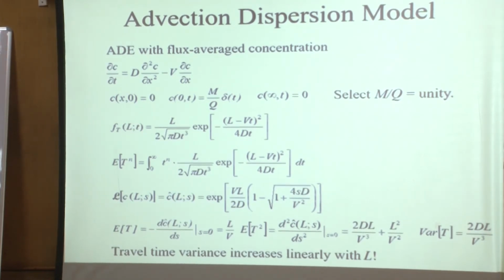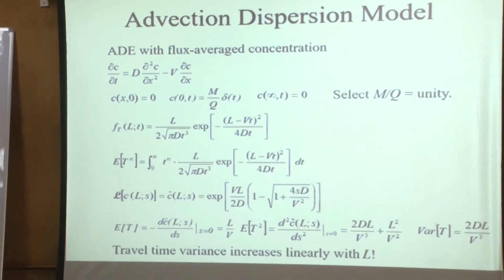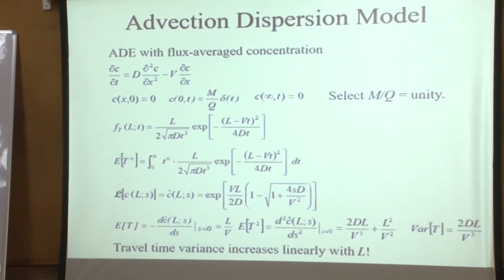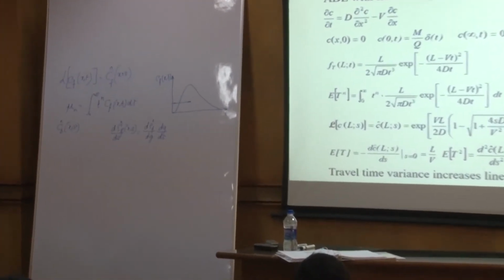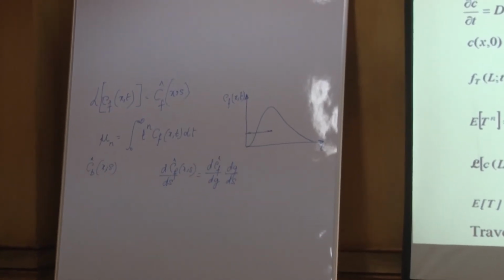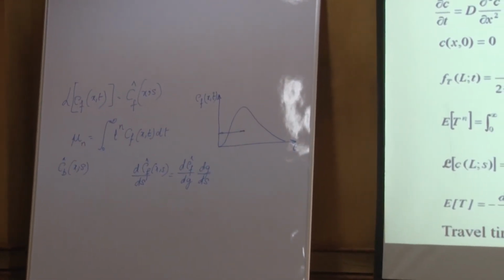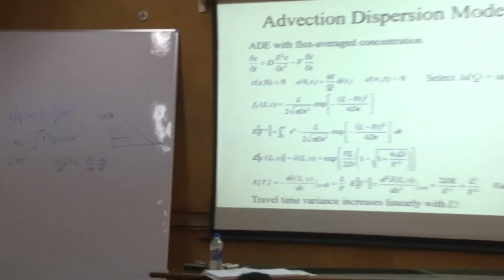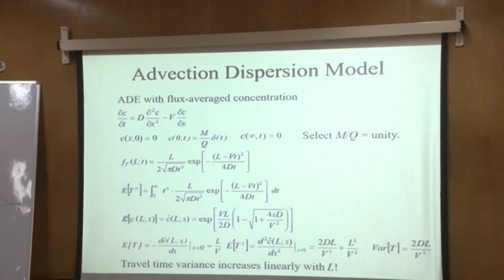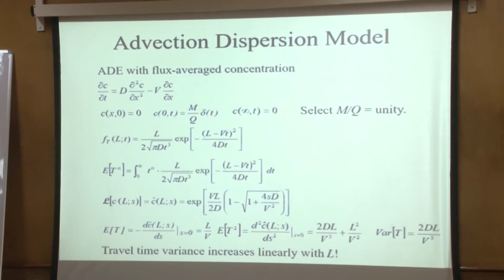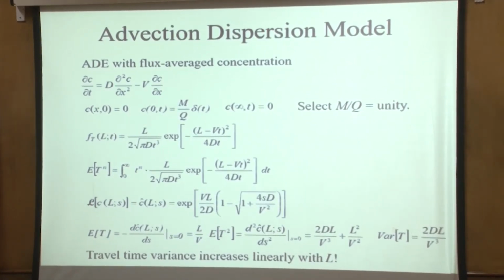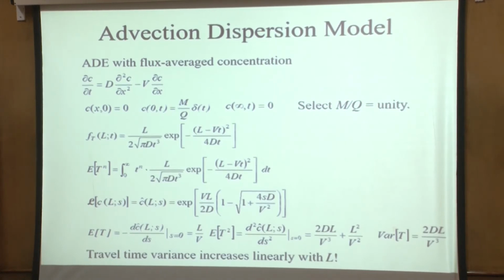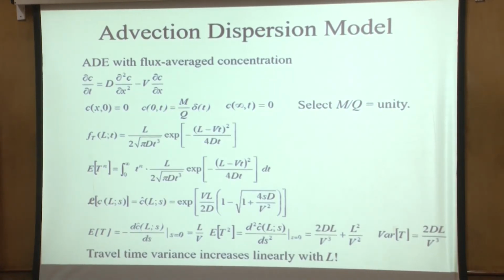So of course, we did all this because we believed in this model. We believed that the advection dispersion equation exists. I did not have to fit this because now it's a PDF. I don't have to actually fit the ADE, or what is called a Fickian PDF in this case. Professor Guha talked about log normal distribution. I could go ahead and fit the log normal distribution to it. He talked about the gamma distribution. I could fit a gamma distribution to it too. Basically what I'm observing is simply the travel times.